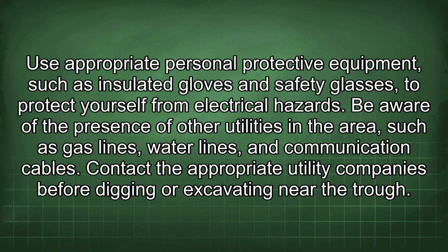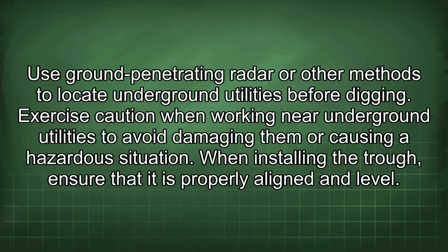Be aware of the presence of other utilities in the area, such as gas lines, water lines, and communication cables. Contact the appropriate utility companies before digging or excavating near the trough. Use ground-penetrating radar or other methods to locate underground utilities before digging. Exercise caution when working near underground utilities to avoid damaging them or causing a hazardous situation.